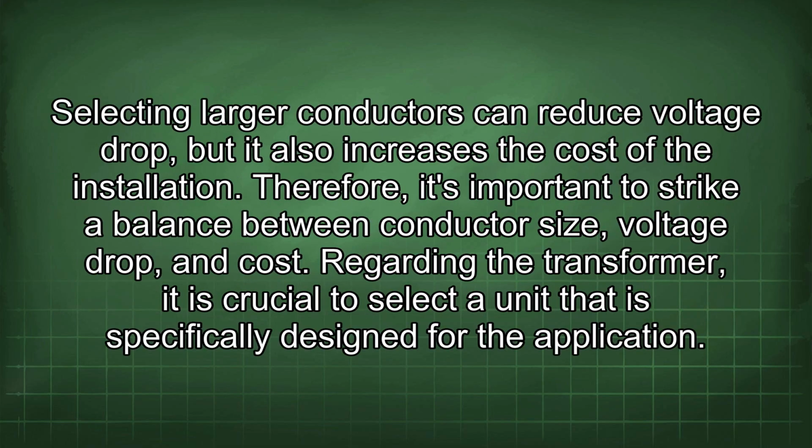Selecting larger conductors can reduce voltage drop, but it also increases the cost of the installation. Therefore, it's important to strike a balance between conductor size, voltage drop, and cost.